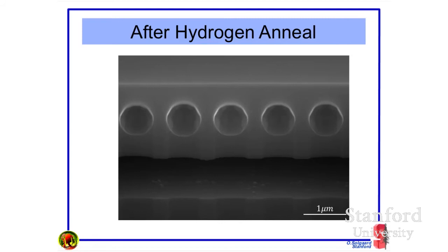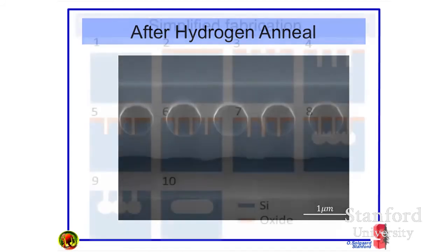And the really, really nice thing about it is that these are single crystalline silicon, and they're extremely small, and those two points hang together, because by making things out of crystalline silicon, I can make things very small and still have them be very, very robust. I can control the process better, so I can go to very thin films and so forth. So this is a very, very powerful MEMS technology.